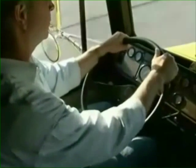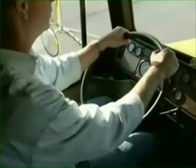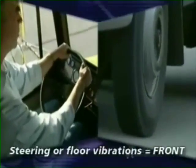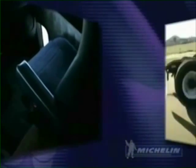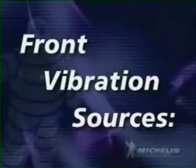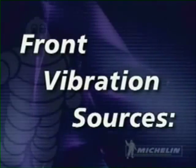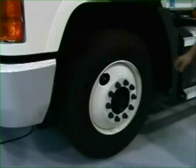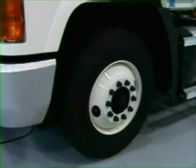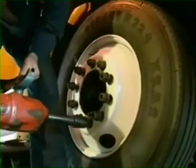As a general rule of thumb, if a vibration is being felt in the steering wheel or floor, the source is usually in the front end of a vehicle. If a vibration is being felt through a seat, then the source is usually coming from the rear end of a vehicle. Vibration being felt in the steering wheel can be the result of several different inputs. For example, number 1, the front tire wheel assemblies are out of balance or improperly mounted on the vehicle.